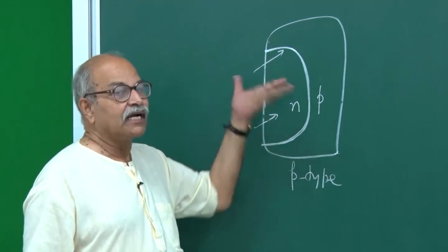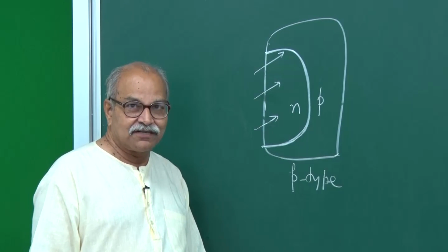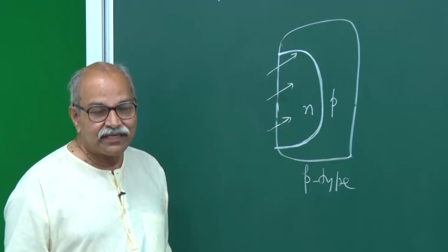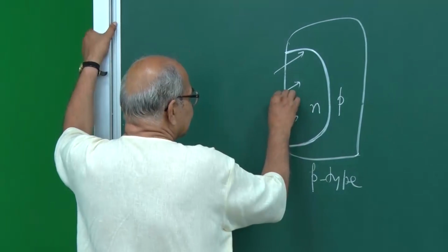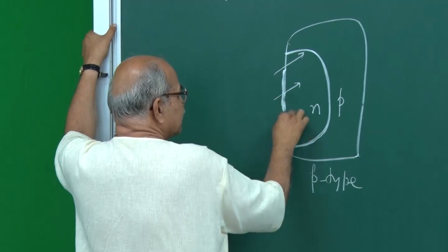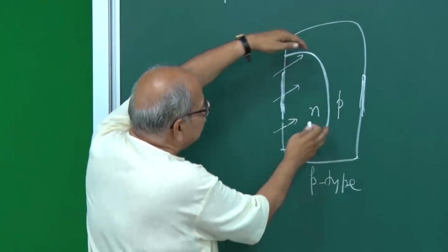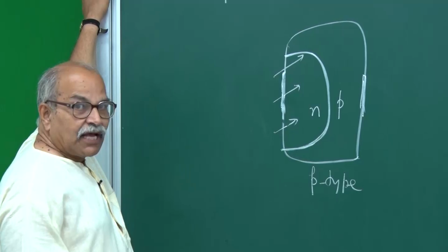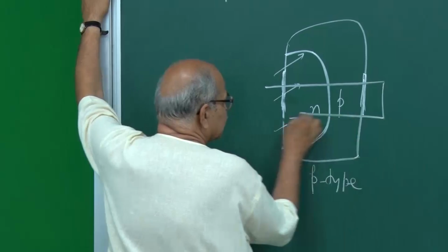So, this is p-n junction, and if you want to use it for external world, you should have metallic contacts from where you can connect wires and put this into circuits. So, once again in a very controlled fashion, aluminum or some metal is deposited either on the back side or on the front side itself. You can have a metallic contact here. So, for our discussion, I will be drawing this part of the system.